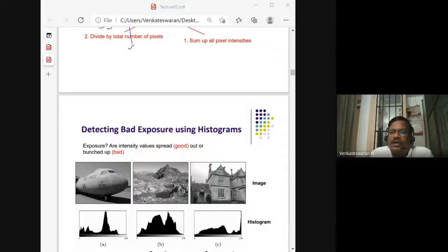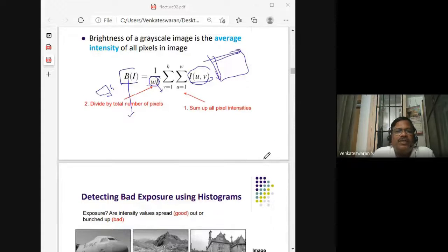So in general, if there are any spikes in a particular region, it will be very clearly understood if one of these values, or a combination of values, is slightly high due to noise or something. So you take one portion of the image which has 3 pixels on this side and 3 pixels on that. There are 9 pixels, since 3 into 3 is 9. So you're taking an average of 9 image pixel values.